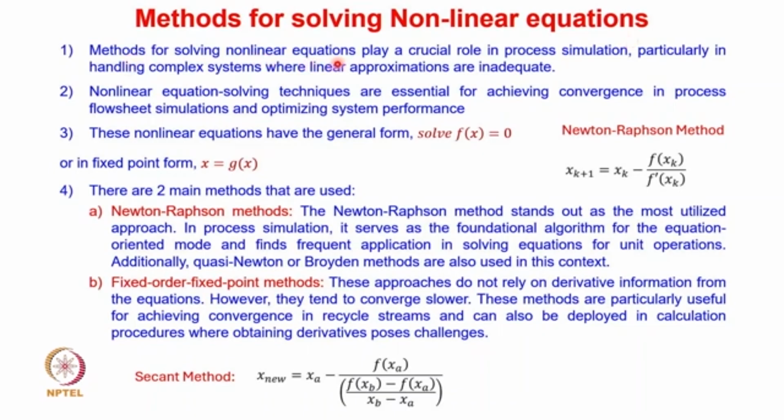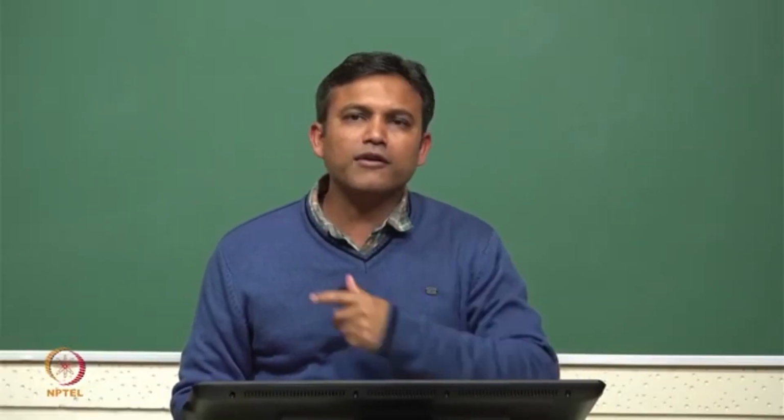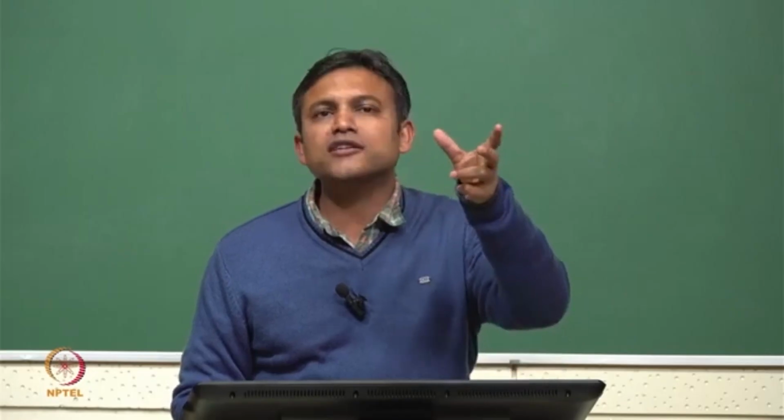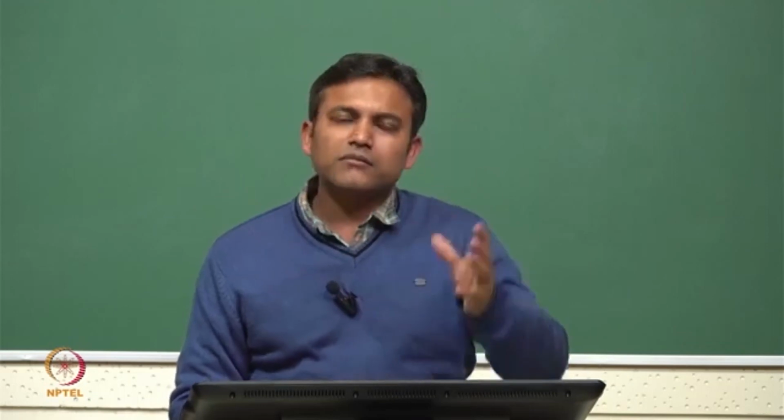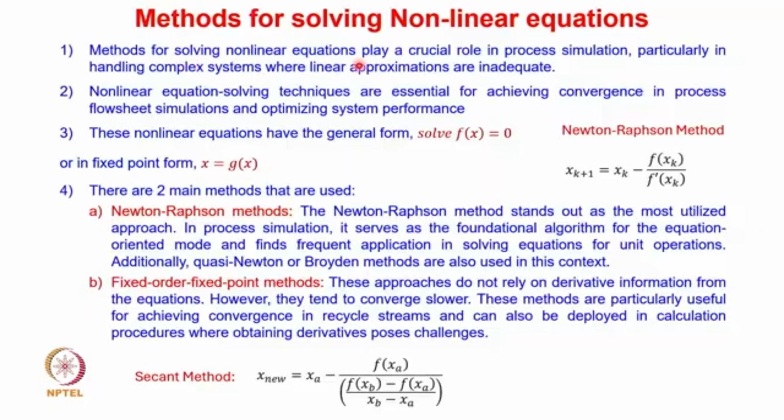Methods for solving the non-linear equations play a crucial role in process simulation, particularly in handling complex systems where linear approximations are inadequate. Remember, initially, when we looked at the preliminary flowsheet designing, we used linear balances, isn't it? We linearized all our equations, but that linearization gives you only an approximate solution. Once that initial part is done, you want a more accurate solution, and you can get that by solving the non-linear equations. Non-linear equation solving techniques are essential for achieving convergence in process flowsheet simulations and optimizing the system performance.